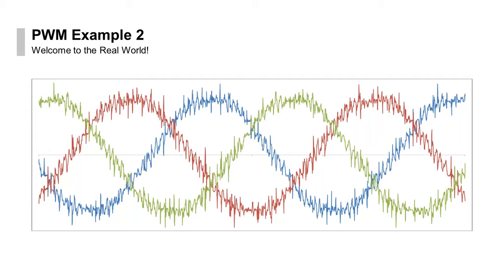a real world voltage waveform that I actually collected in the field on some of our 5 kV equipment. Suddenly you can see that this does not look like that nice 6-step waveform that you saw before. Instead, it's pretty aggressive looking, especially when compared to that ideal sine wave.